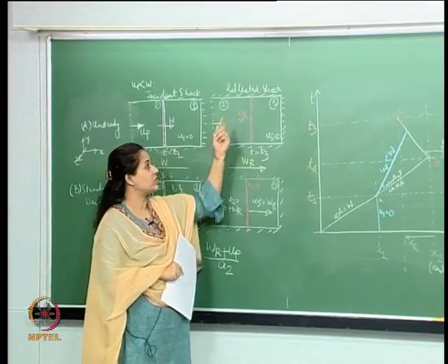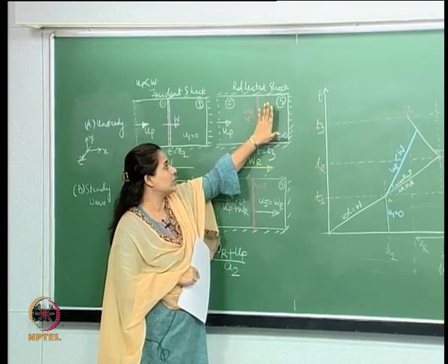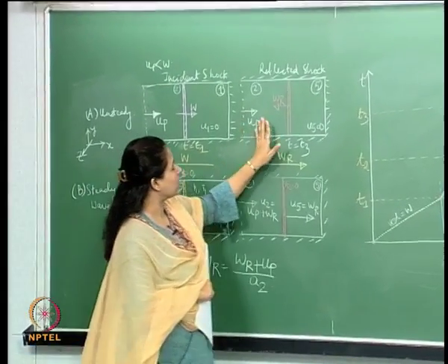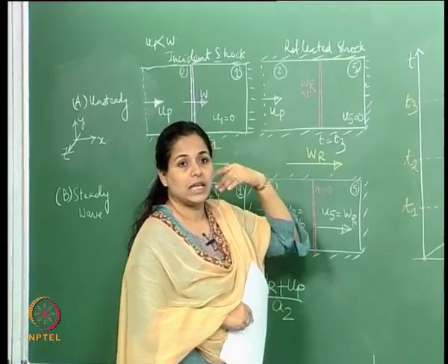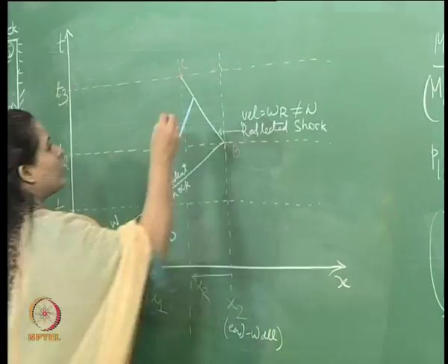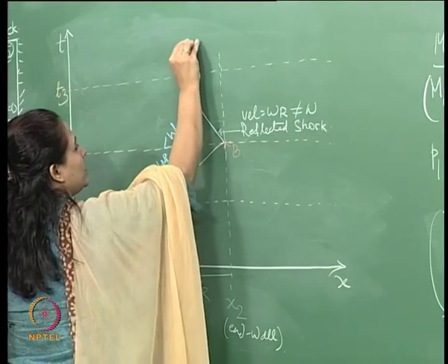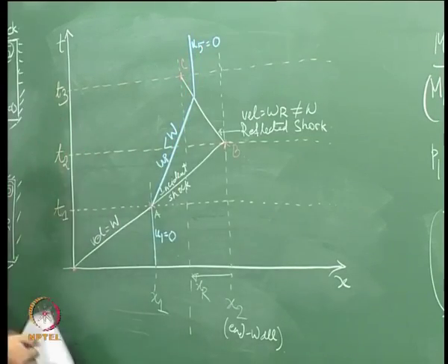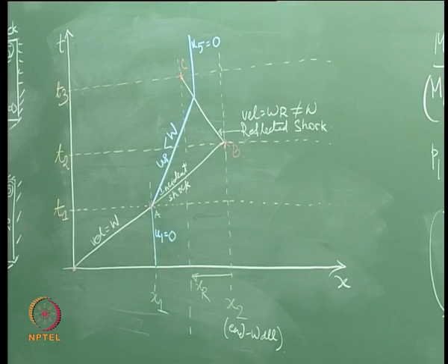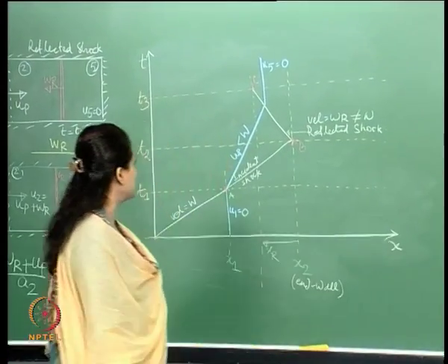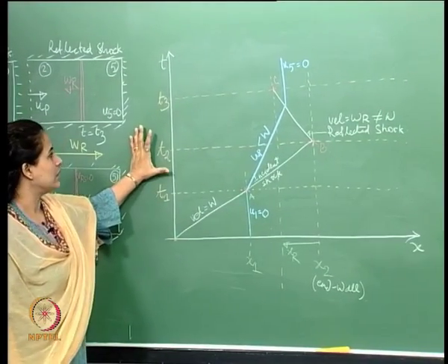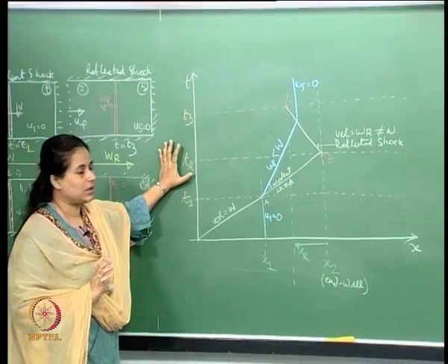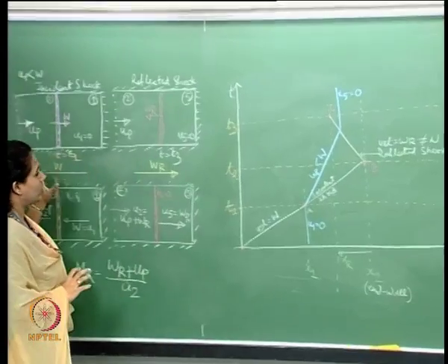So again it meets this reflected shock, and the shock is reflecting because there is a sudden stop, so that the entire fluid here is going to come to a stop. So the moment the particle comes here, intersects the reflected shock, it again stops completely, right. So therefore the velocity out here again will be 0. Now it has reached the region 5, which is again equal to 0. So this is a graphical, interesting way to understand the functioning of the shock tube.